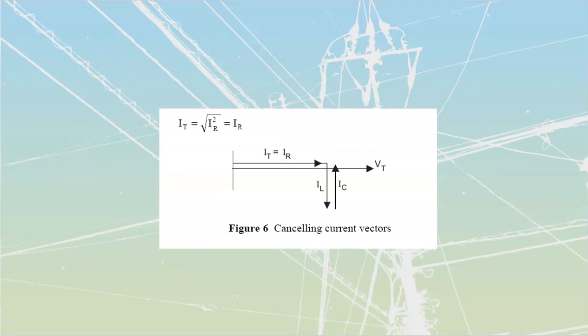The next little section inside your binder talks about parallel resonance. And parallel resonance is really cool inside of a parallel circuit, because we get cancellation of our current. If you take a look at this IL and this IC, we see that they are going to be at the same value. We see that there is inductive current, there is capacitive current, but they're happening at opposite times.